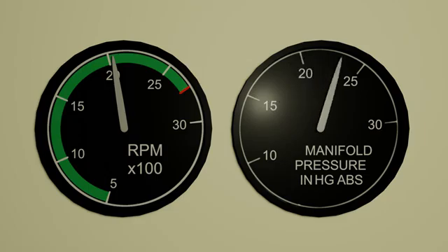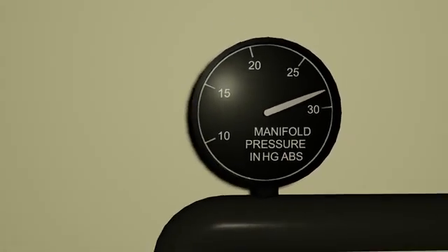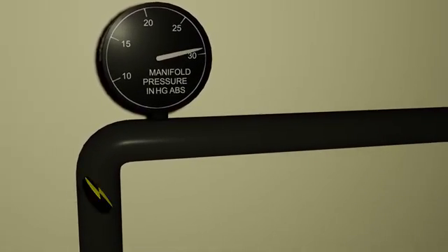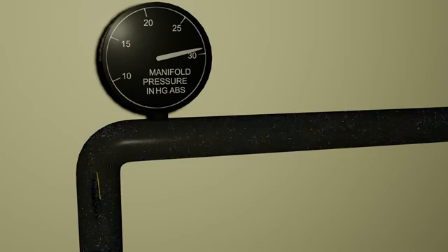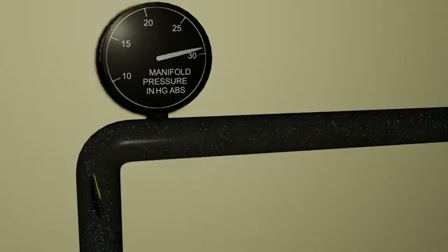Instead of pressure, let's actually think of it as manifold suction. The manifold refers to the intake manifold, the pipe for intake air, downstream of the throttle plate. What's responsible for creating this flow of air? Well, it's each of the pistons in their intake stroke. If the throttle's opened, the engine would consume all the fuel-air mixture it can, and it would run at full tilt. A throttle restricts the engine.